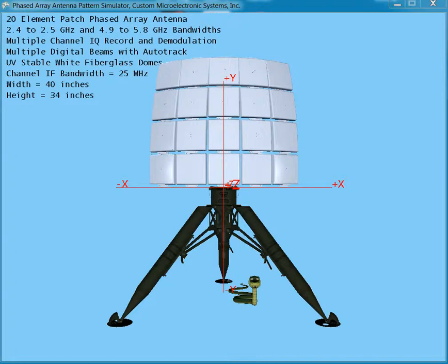It only simulates phased arrays that are flat and not spherical, as you see here. Following versions will handle phased arrays that can be conformally mounted to surfaces that aren't particularly flat in structure. Inter-element spacing is the same between all elements, set at λ/2 in this example.